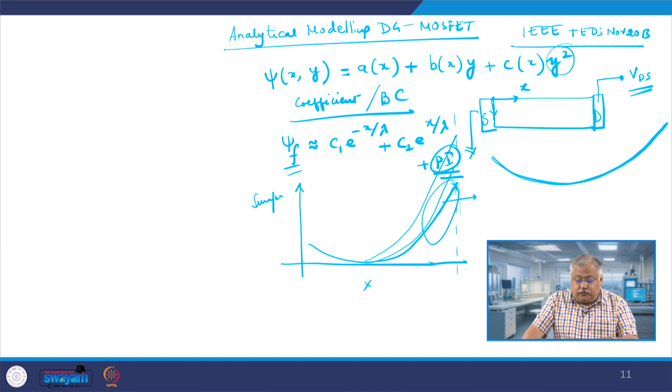Now, we also found out in this paper the threshold voltage of the device. How do you define threshold voltage? That gate voltage at which the channel is inverted, as it becomes as much n type as it was initially p type.